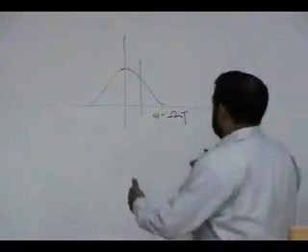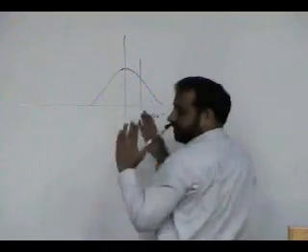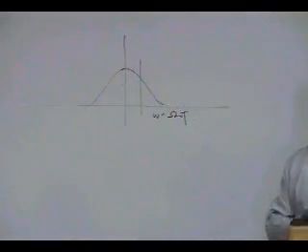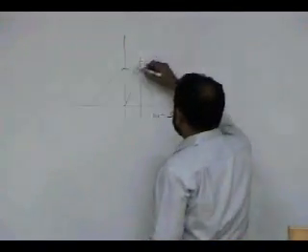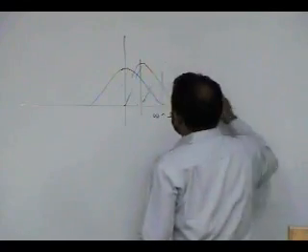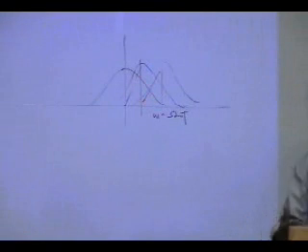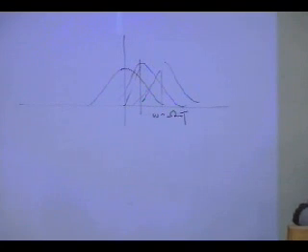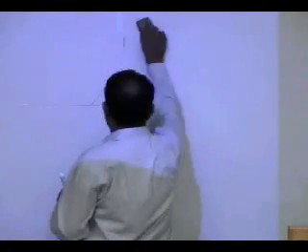If the entire spectrum is within minus pi to pi after this translation, you are fine. But if it is not, then you are in trouble, because at every 2 pi you will have a copy, and at every other one you will have a copy. So there will be not only one, there may be many copies which are causing aliasing. So this is a problem: this technique is only good for band limited signals.